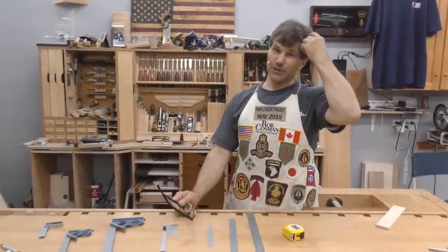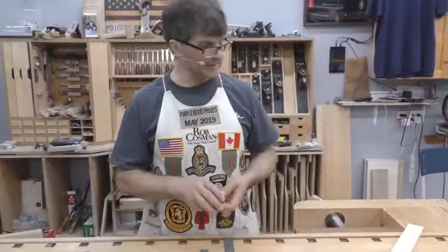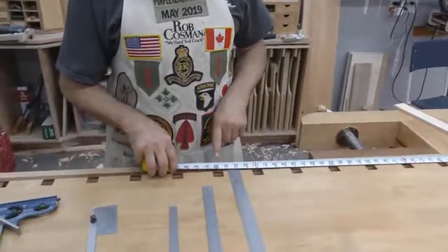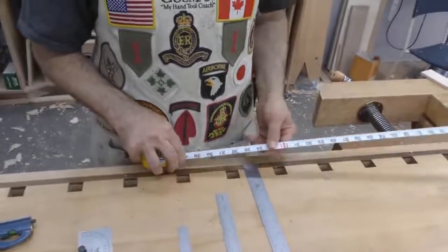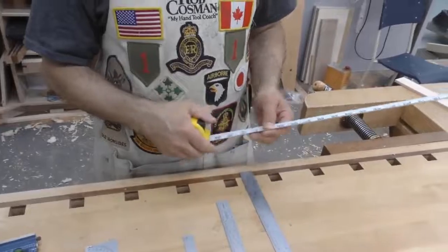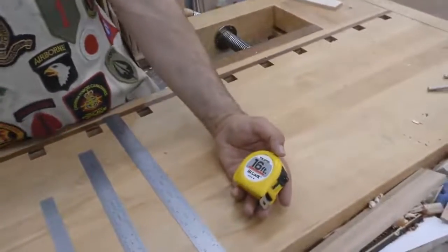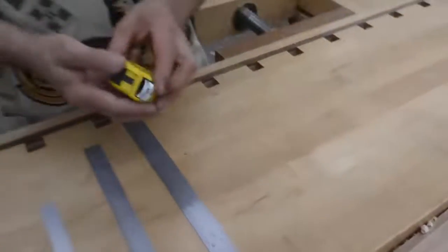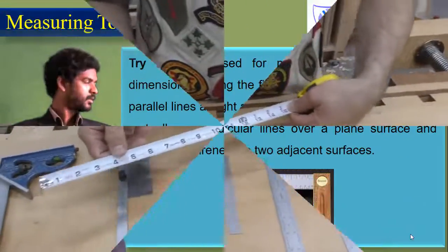In general, rules are used for measuring dimensions. For measuring and setting out dimensions, various types of rules are used in the carpentry shop. Steel rule, a stainless steel rule of length 30 cm and 60 cm. Flexible measuring rule, for measuring large dimensions as well as curved or angular circle dimensions. Okay. The next one is the tri-square.